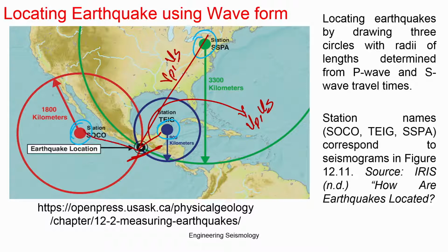Similarly, this velocity will be different as the geological terrain varies. The wave characteristics are a function of the stiffness and density of the geological material. The P wave is a function of the constraint modulus, and the S wave is a function of the shear modulus of the material. So that varies, and then these values also vary.